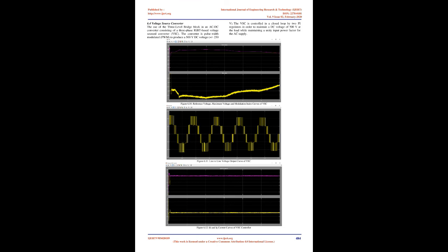The simulation results for the duty cycle, D, which is defined by the use of the P&O algorithm in the MPPT algorithm for getting the maximum power point tracking in the PV module. Figure 6.5, irradiance, temperature, and duty cycle curves for PV module.